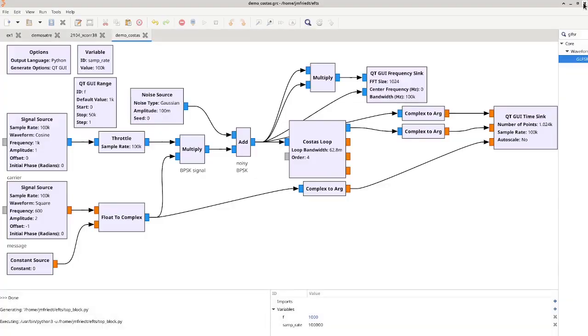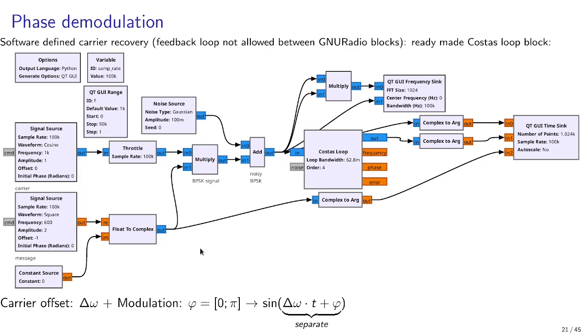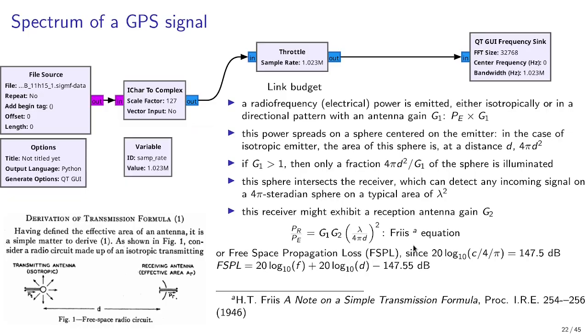sampling rate. The Costas loop is a core element of any phase-modulated signal analysis, as it is mandatory for cancelling the frequency offset between receiver and emitter. Even if we were to have atomic clocks on our receivers, the motion of the GPS satellite along its orbit will necessarily introduce some sort of frequency offset between the receiver and the transmitter.